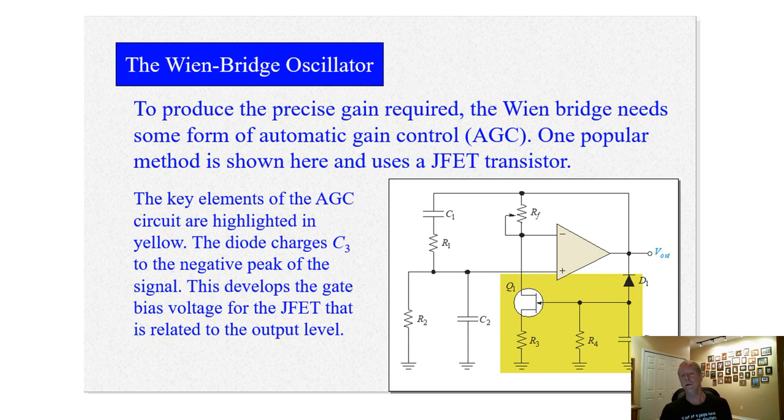Or turned off, and then when it's turned off, because it's a high resistance. Okay. And so once it starts oscillating, it affects this JFET here and changes the gain so that it's exactly 1. Okay, and it charges this capacitor here through this diode, so it negatively charges the capacitor, which shuts off and changes the JFET.